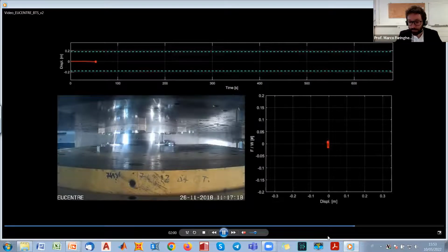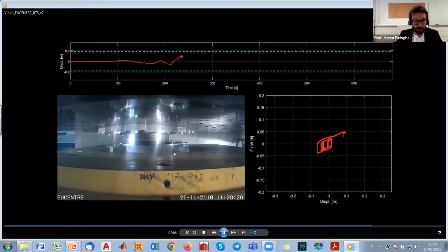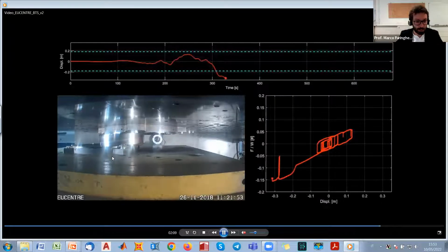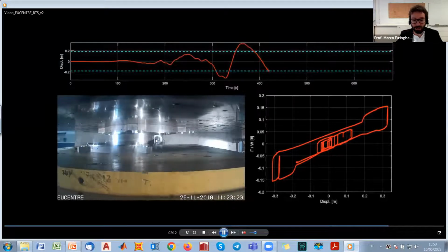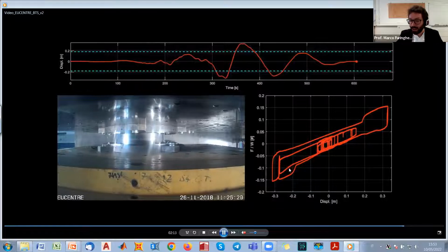You see here, I just try to stop. Just look at the video of the test when it goes now. Okay, you see that there are portions of the materials which are just cut and fall outside the bearing. And these are actually the effects of what we call the overstroke behavior. So the stroke is the maximum capacity of displacement of the device, and as we reach the maximum displacement, you see the increase, but the limited increase in the friction, and also in the other portion of the force displacement loop.